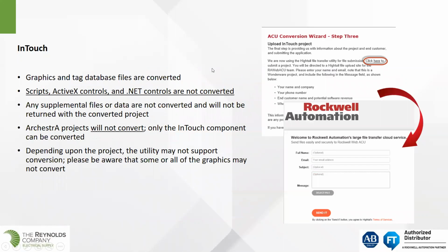So InTouch is a little bit simpler, in my view. Again, the graphics and the tag database files are converted, which are the core of what we're looking for. Now the scripts are not. Anyone that's used InTouch before knows that those scripts were pretty simplistic, 90s type technology. There really isn't a use for those in newer technology. A lot of those scripts can be handled in expressions and through typical animation links today. So those scripts aren't really used anymore. The ActiveX controls were specific, so those aren't really converted.